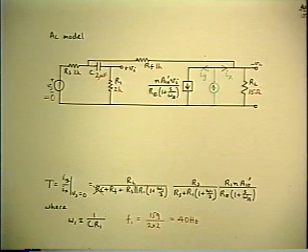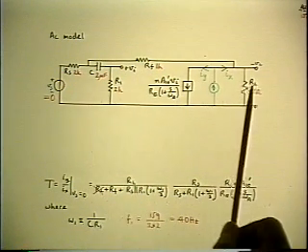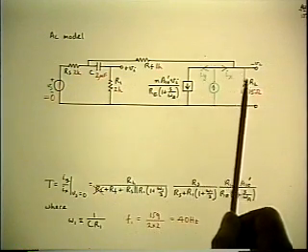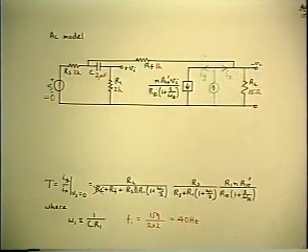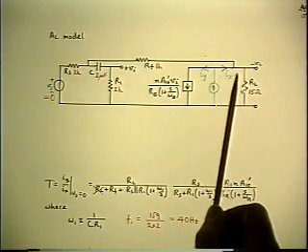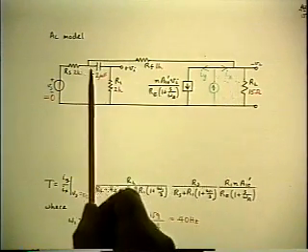Once again, there's all sorts of different ways you can do that. You can modify the model. You can do some of the algebra on the diagram by loop and node removal by Thevenin's and Norton's theorem. You could do all that. Or you could leave the diagram alone and you could do it by successive voltage dividers.